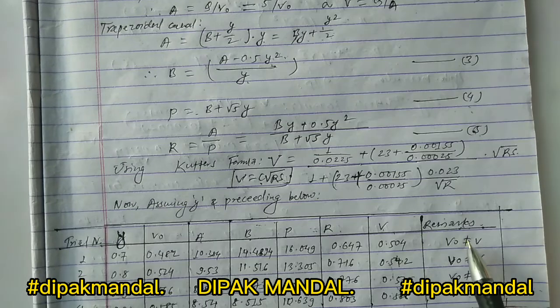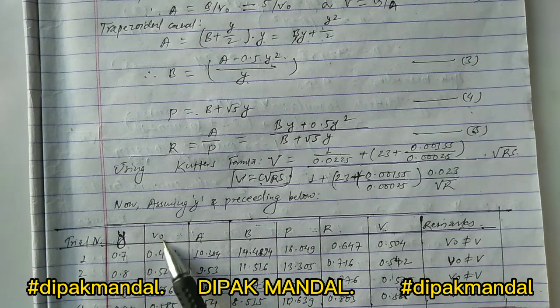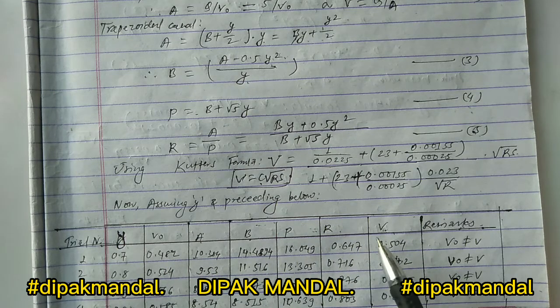Okay, and in the remark we have to compare the value of this actual velocity and this critical velocity. If the actual velocity is nearly equal to the critical velocity, then we have to stop the trial. Until these two values are equal, we have to proceed to the next trial. Okay, so let's see.